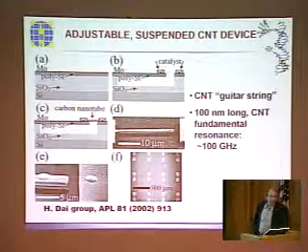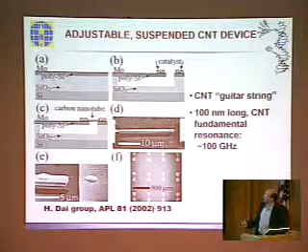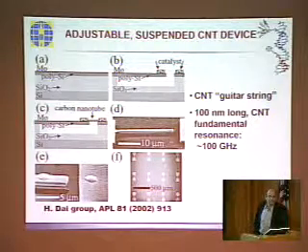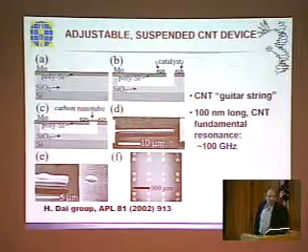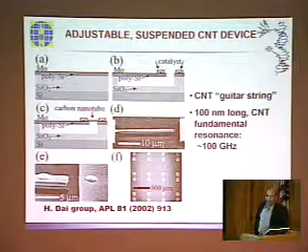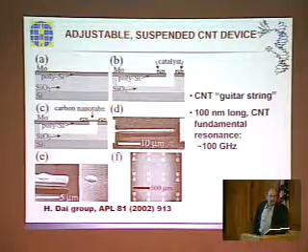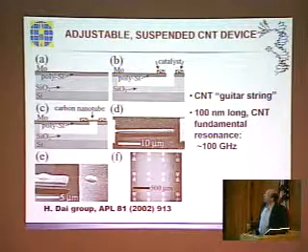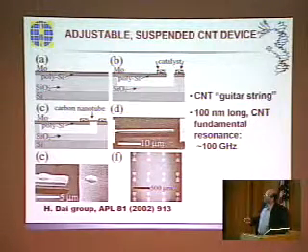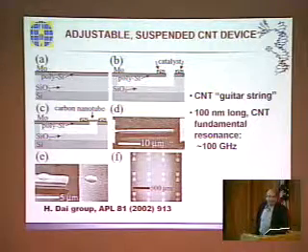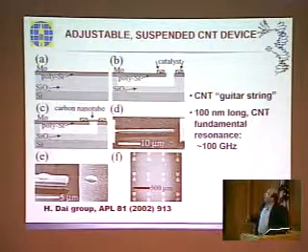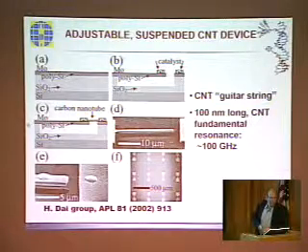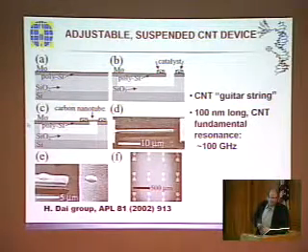gigahertz. And more recent work than this shows that there is a significant piezoresistance in these carbon nanotubes, so it's relatively easy to sense that high frequency motion by measuring the voltage drop across the tube for a constant current. So one can imagine integrated nanoresonators with extremely high frequency, and you can even tune them then by varying the stress by pulling on that cantilever.